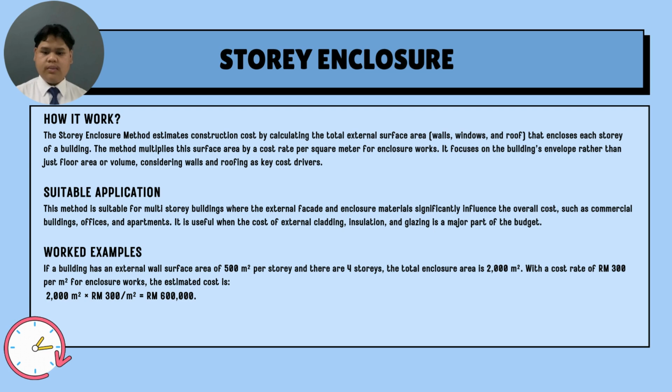The storey enclosure method estimates construction cost by calculating the total external surface area, walls, windows and roof that enclose each storey of a building. The method multiplies the surface area by a cost rate per square meter for enclosure work. It focuses on the building envelope rather than just floor area or volume, considering walls and roofing as key cost drivers.